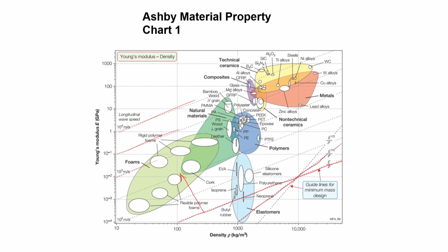So, suppose my cutoff level in this case is 1 GPa, that in no way I can have a probe whose modulus of elasticity is less than 1 GPa. Then this is the line that we have to see, and then in this line I have to see what are the materials that are coming up above it, like CFRP, like Si3N4, some titanium alloys, though they are mostly here.